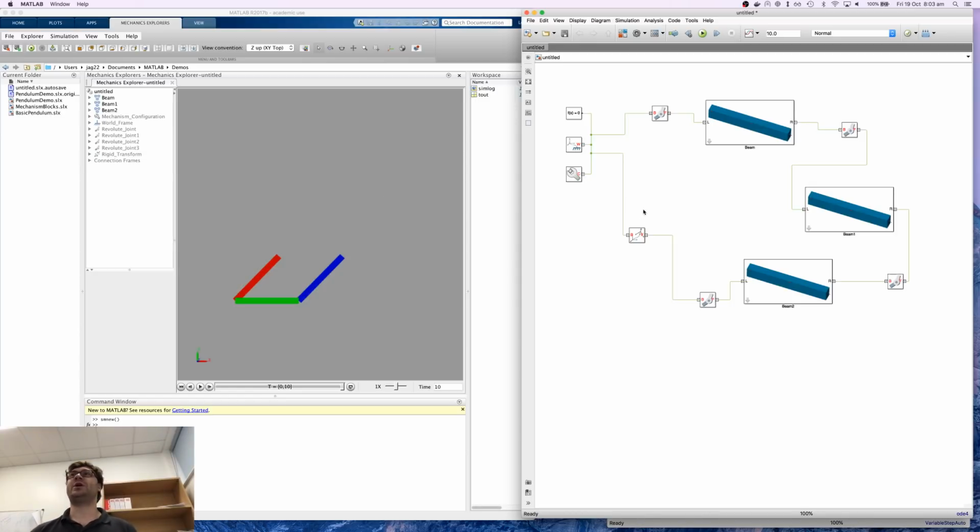With your car convertible roofs, you're going to have lots of multiple bars, and yes, you could calculate that manually using your solid mechanics notes, but it would take you a long time. And actually, this is the power of using these models. It's actually to generate these torques for you. To do this in this model, we're going to use the advantage of this revolute joint to determine the torque we require for a specific position.